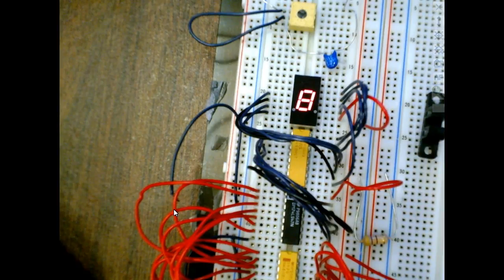The 7447 does not run the decimal point, so we have to run the decimal point externally. I'd have to come up with some circuit to run it, because a lot of times we don't use the decimal point. All we want is a number. If you look at what the 7447 decodes, it's A, B, C, D, E, F, G, but there's no decimal point, because how does it know where the decimal point is supposed to be lit? It doesn't. So that answers your question?